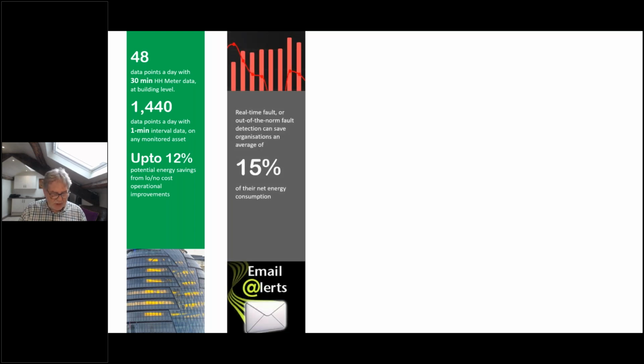Now, a lot of the time, there's so much data out there. A lot of people just want to manage by exception. So a lot of software in these energy management platforms, we're no exception, can provide alerts. So you can set up, I want to know when consumption goes above a certain level, when amps goes above a certain level. I want to be informed, and then you can take remedial action. So it's managing by proactiveness, really.